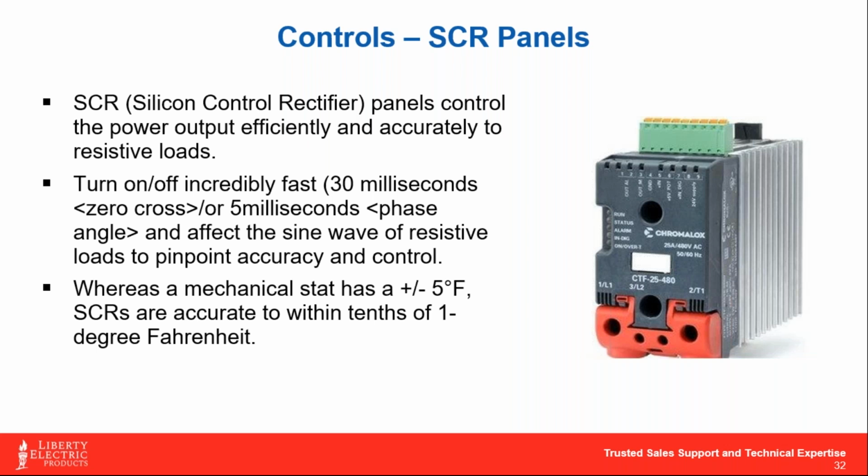What I like about this feature is that on startup, you're typically soft starting these heaters so that you're not getting that massive inrush current of, say, 480 volt or 600 volt directly onto a contactor that's being turned on and off like a light switch every 10-15 minutes. Over time, and it wouldn't take very long, you could burn out those contactors just from the amount of voltage going through them. Something like an SCR helps to soft start that process, which means longevity for your heating elements.